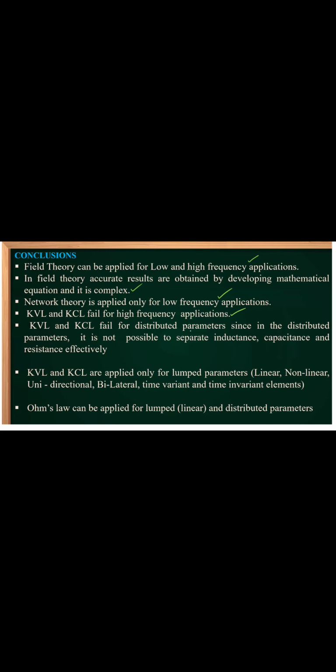KVL and KCL fail for distributed parameters. They are applied only for lumped parameters, since in distributed parameters it's not possible to separate the inductance, capacitance and resistance effects. That's why KCL and KVL are valid only for lumped parameters. They fail for distributed parameters.